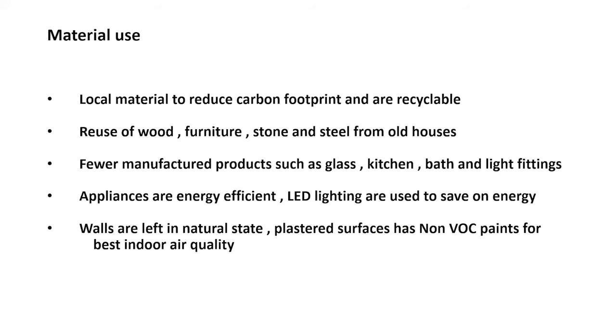So while we are choosing material, it is important to see the carbon footprint and recyclable part. Carbon footprint is important because we are sourcing far away from China or Italy or Scandinavia, wherever it is, so it is very important to choose local material with the lowest carbon footprint. And reuse as much as possible existing wood or stone or steel from an old house. I'll give you some examples of those.